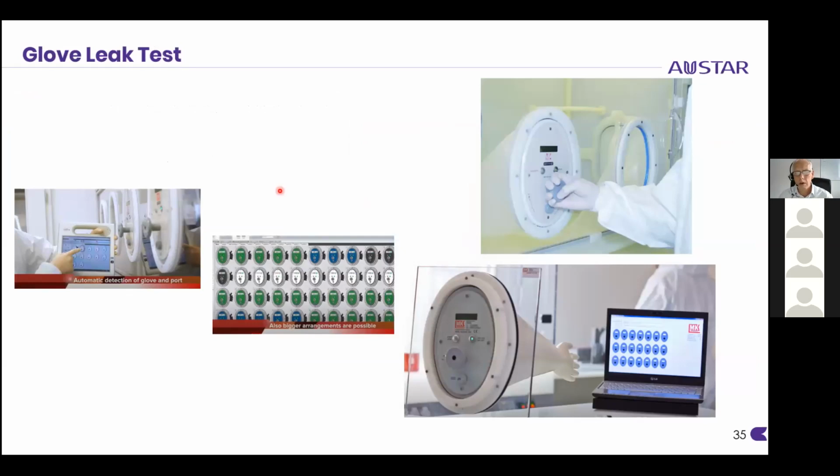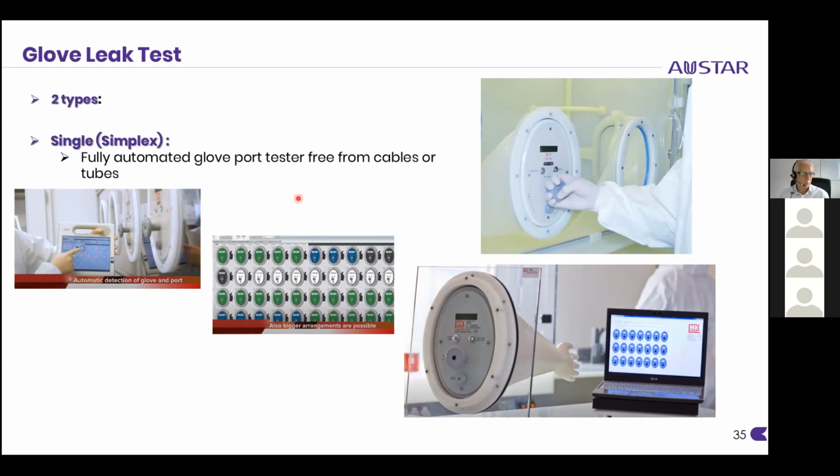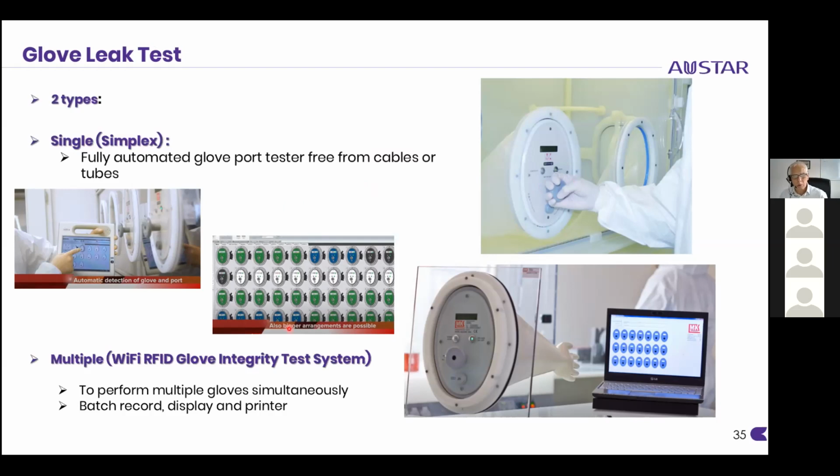Glove leak test, very important. State-of-the-art glove port testers, very GMP compliant, no airlines and no wires connected to them. They can be totally wire free to carry out the test by inflating the glove and testing for leakage over time. So we have two types. We have a simplex for single port testing, and also there's a multiple port test system which can send Wi-Fi signals away to a laptop computer to transfer all the test data and also store it for batch record, and then you can have printouts to be compliant.